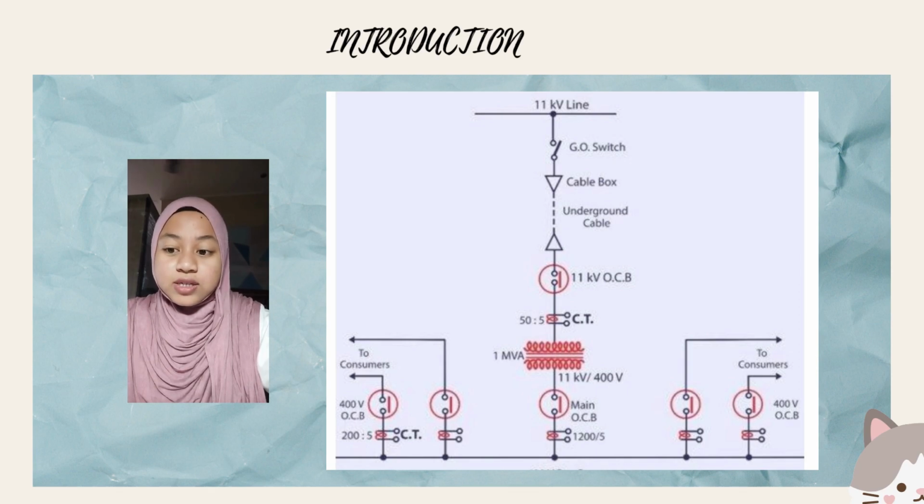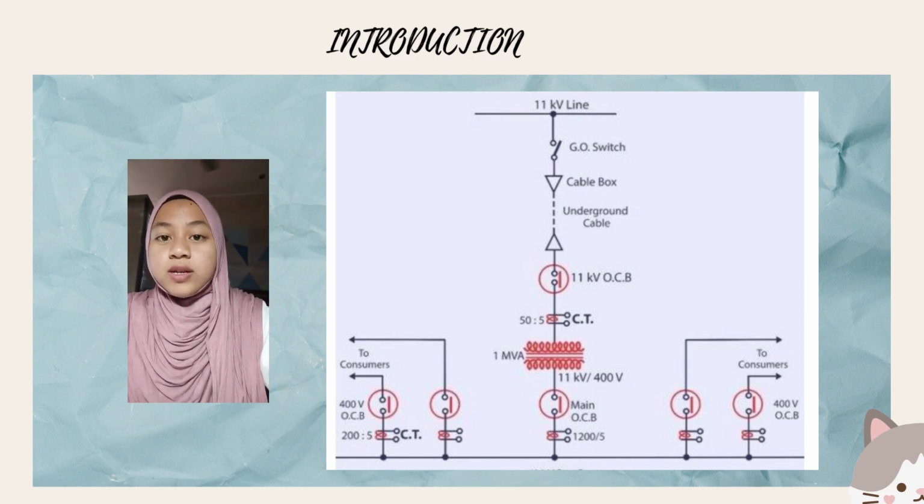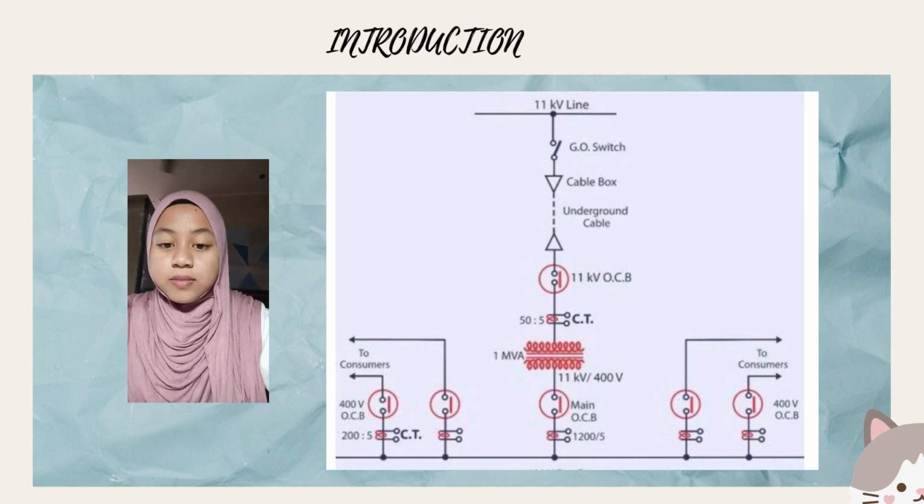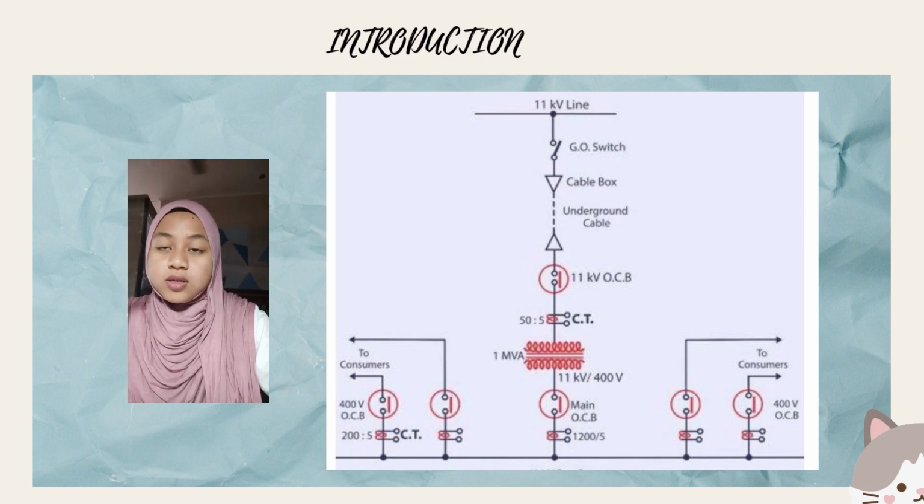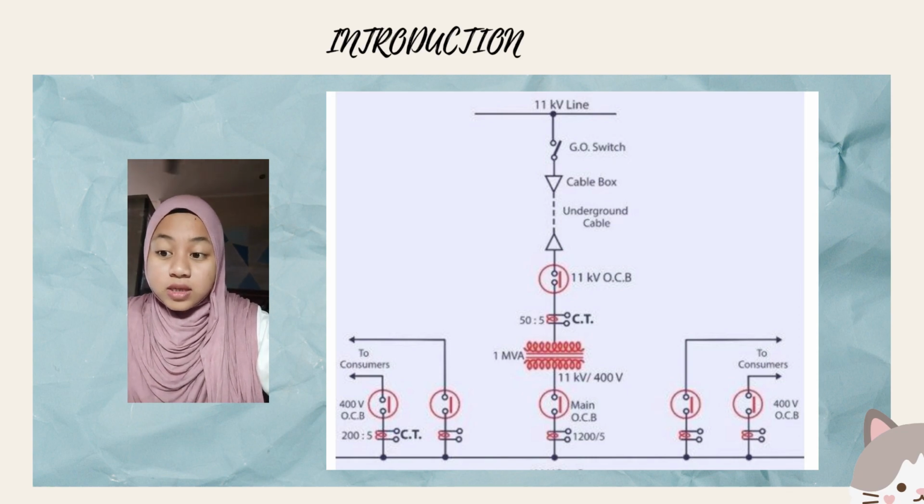to the utilization. The next symbol is the earth fault relay in the single line diagram. Its function is to cause any component that experiences a short circuit to be removed immediately from the service. Other than that, it also acts when a component of a system begins to behave abnormally, which could harm the system as a whole or impair its ability to function normally.